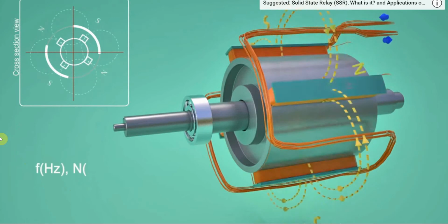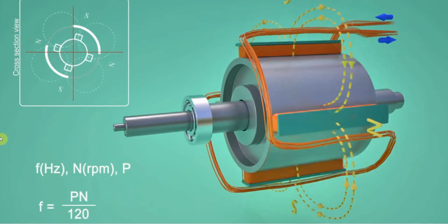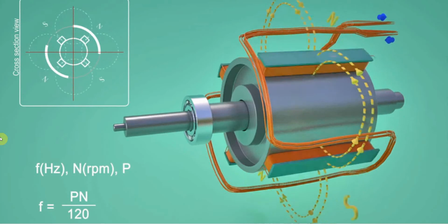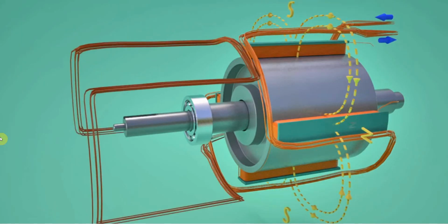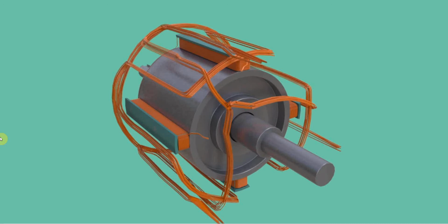It is clear from this relationship that the frequency of electricity produced is synchronized with the mechanical rotational speed. For producing 3-phase AC current, 2 more such armature coils which are in 120-degree phase difference with the first are put in the stator winding.